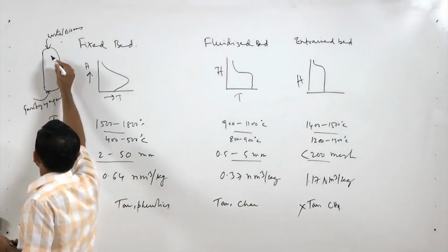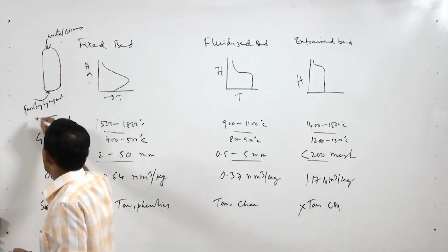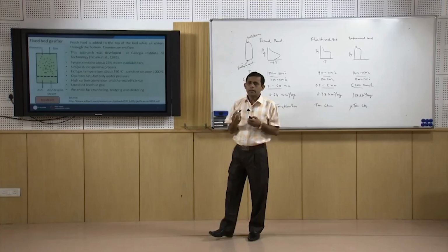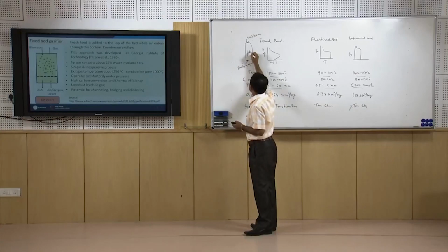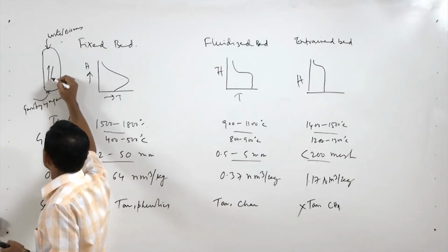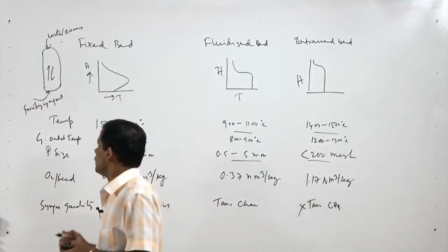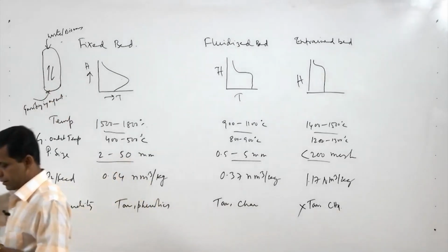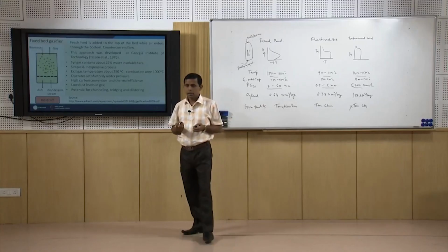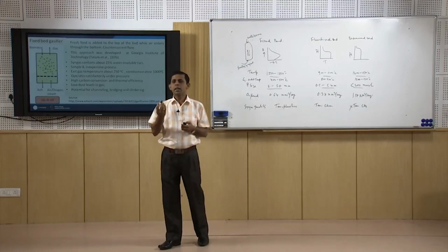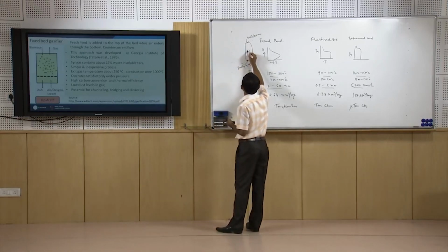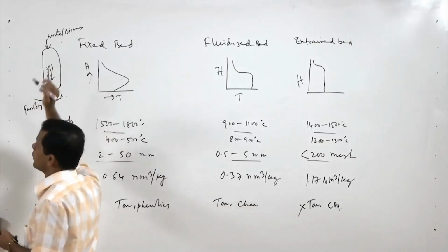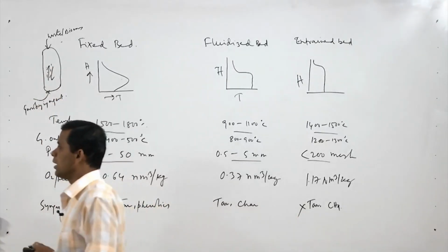So, the biomass and waste and the gasifying agent are getting less time for contact because there is countercurrent flow, and when the material is coming down, bigger size particles and the gasifying agent is going up. So, there is a good chance of blocking and channeling. So, there will be a chance of channeling and bridging.